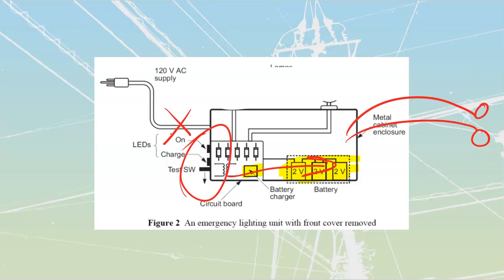We've got another one that's going to be a low voltage battery disconnect. If we run this for a long time, say a power outage that lasts a couple of days, we're going to continue to draw from here. And so there gets to this point where these batteries are going to get too low in their voltage. Batteries can get damaged if we deep discharge them. So we can have systems that will disconnect these.